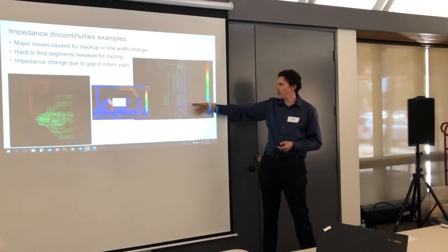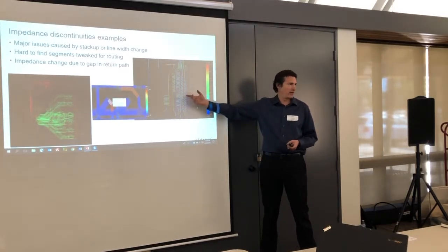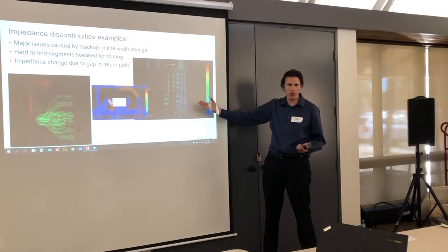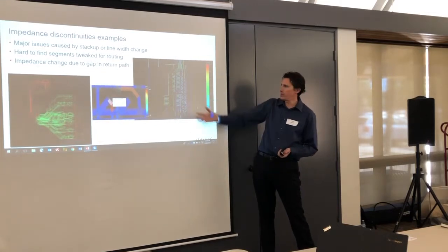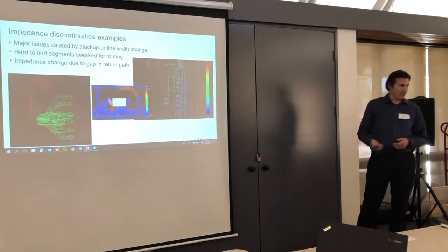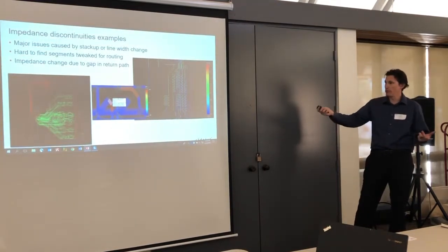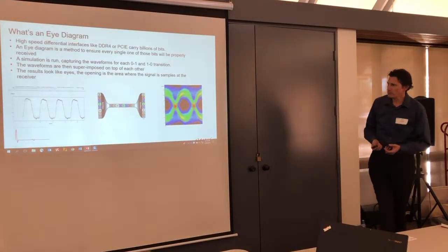As a PCB designer, are you going to fix that by changing the width of those lines just in that point? No, you're not. Then you have to figure out a different routing strategy, find out how important it is for these things to have a good reference plane or something like that, right? Maybe at one point in time they did have a solid reference plane, something changed, and then now you realize, oh, now I might have an impedance problem.